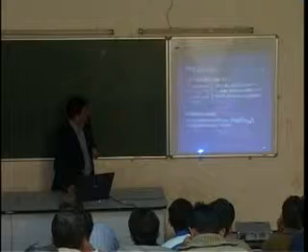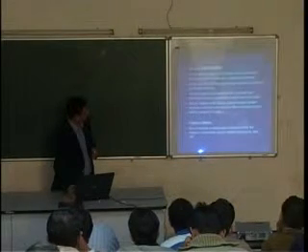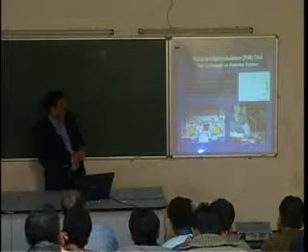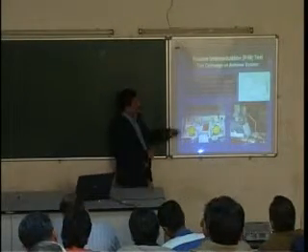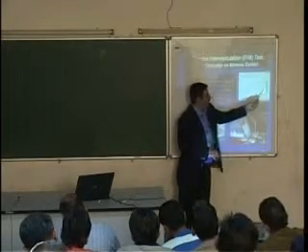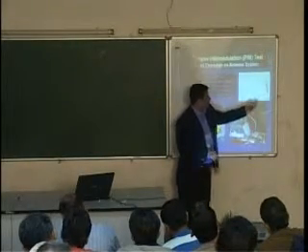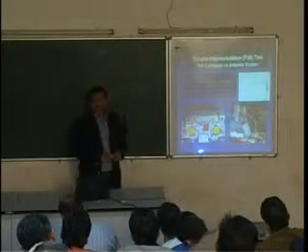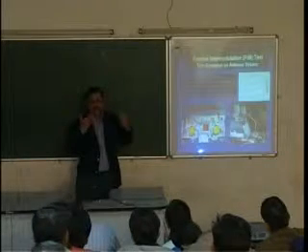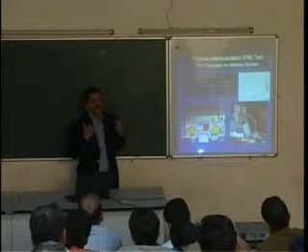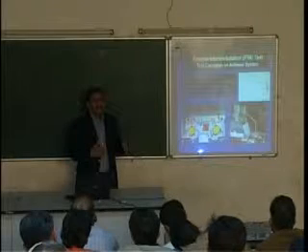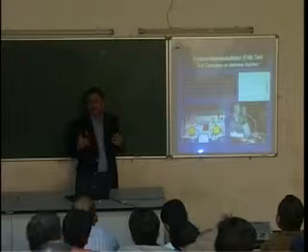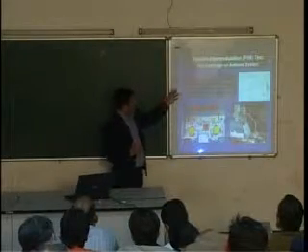So how do we measure it? Suppose we have an antenna and this is the feed, and we pump one signal in with the necessary power. We predict what type of harmonics can be there in the system, if at all any PIM occurs, and then we design tailor-made filters and receivers in such a way that we get sufficient dynamic range.